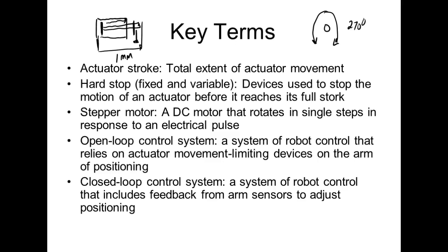But you'll just see systems that are open loop, where if something's not there, the robot doesn't know. It'll go over there and try to pick it up and do everything it's going to do, but there's no sensor to tell the controller that there's nothing there. That's on several things. And why? Because the more sensors you add, the more expensive the system is. If you add a sensor, then there's got to be something to monitor that sensor, right? A lot of open loop.